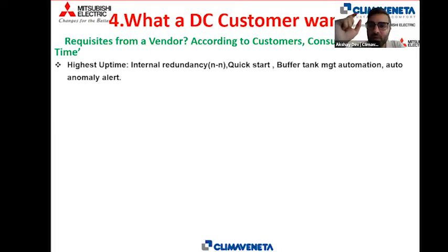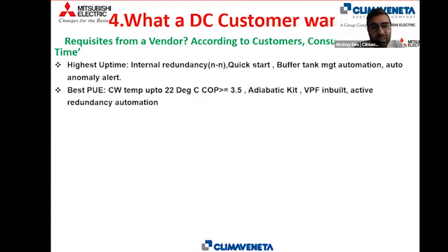So the company you're choosing, please ensure they have expertise in buffer tank automation. Best PUE, of course, customer will say, I want the best PUE, right? Because that is what amounts to him getting a capital gain in there. So chill water temperatures, how do you get best PUE? We spoke about this. Higher chill water temperatures equals better efficiencies.